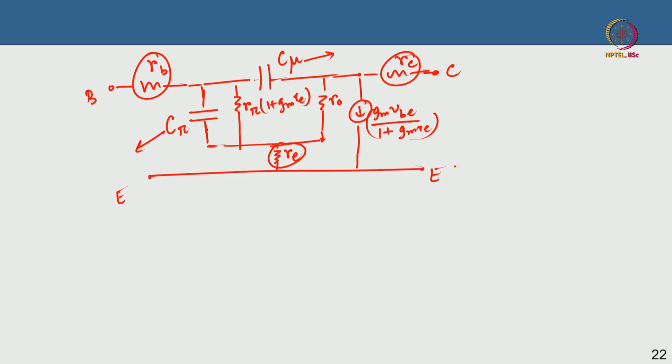So, to start with, the voltage that you are applying at the collector, VC, the true voltage that will appear across the intrinsic collector is not equal to VC. This is the applied voltage. In the absence of parasitics, this is the true collector voltage at the collector terminal of the intrinsic device. But in reality, because of the parasitic resistances, you will have to drop some voltage, that is IC times RC. That is the extra voltage you are dropping on the collector resistance, correct.